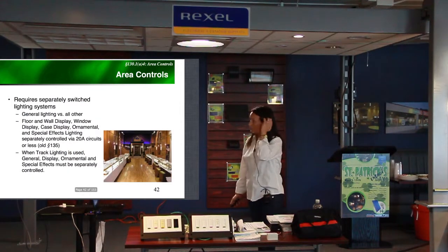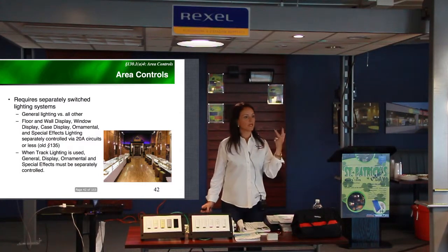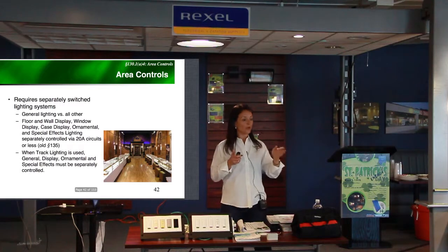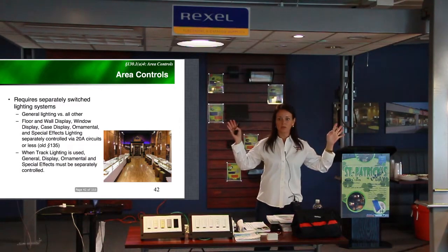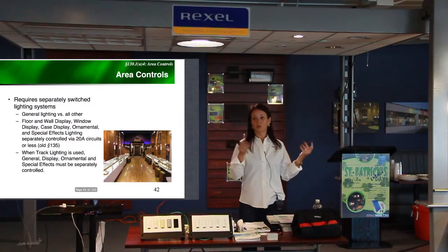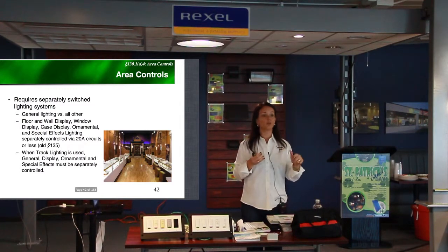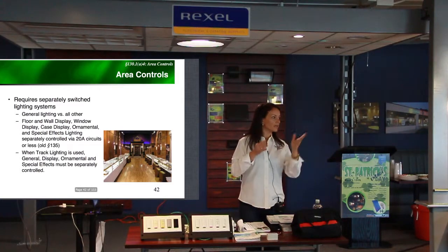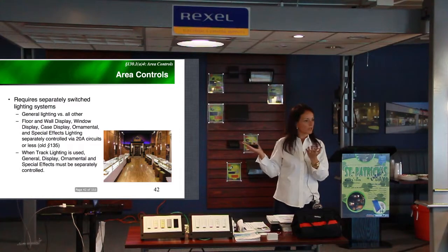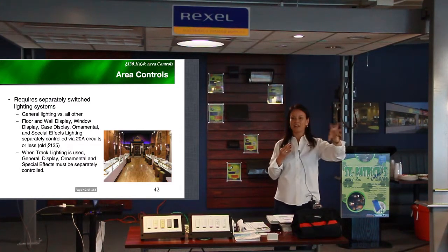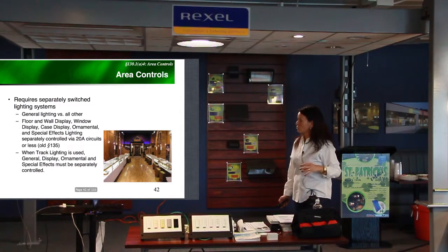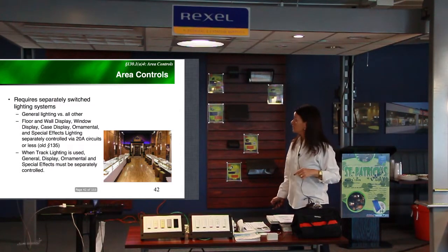And just a reminder, if there is case lighting or accent lighting or display lighting, those need to be switched separately. Code requires that you cannot have one master switch for everything. In a space like that, you guys probably have ways to access every single fixture on its own using the lighting control system you chose. But in a regular scenario, we have case lighting and display lighting, probably with wall switches or some kind of point of control located in the space.